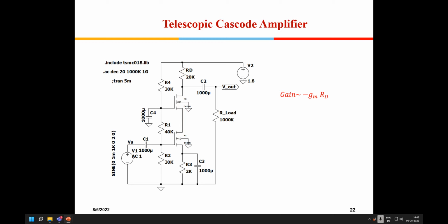As per my understanding, this M1 is a common source amplifier, and this is a common gate amplifier, and for a common gate amplifier the current gain is 1. No, I'm talking about M1, the bottom one. This is the common source amplifier. The top one acts as just a load. We are giving the bias voltage, and it's a transistor. We will ignore that as a common gate as of now. Give me 1 minute, I'll come to that aspect also.